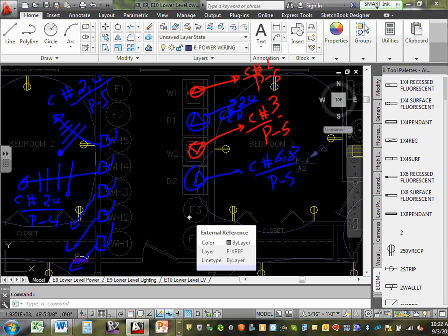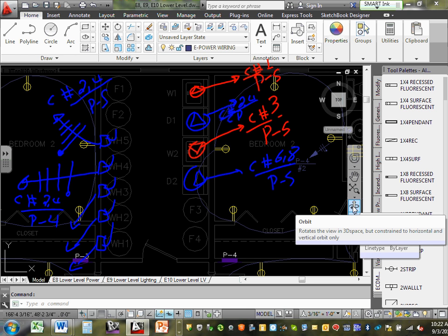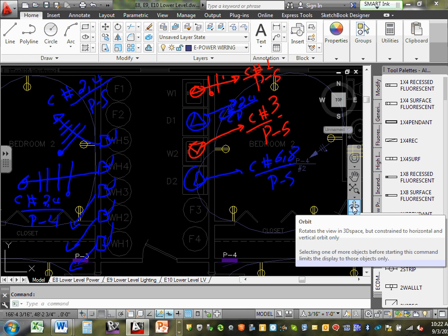Any comments, any questions, guys, about all these? Oh, for the washing machine, it's very easy. It's going to be a ground and a neutral and a hot. That's how they're all going to look. For the dryer, it's going to look like this. Here's 1, here's a neutral, here's a hot, and here's a hot.